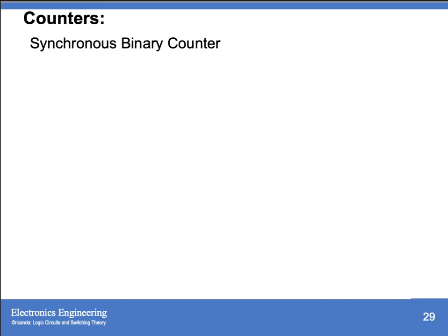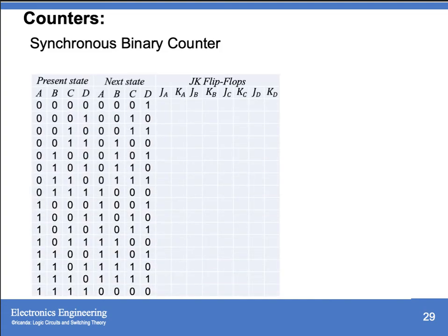Because if we see the determined sequence in our previous example, when x is equivalent to 0, your sequence is from 0 to 7 back to 0. So that is a determined sequence, increasing by 1 every time a clock pulse occurs. So that is what you call your binary counter. So we have that example. This time it is a 4-bit counter, and it is a binary counter because it increments 1 binary data per pulse.